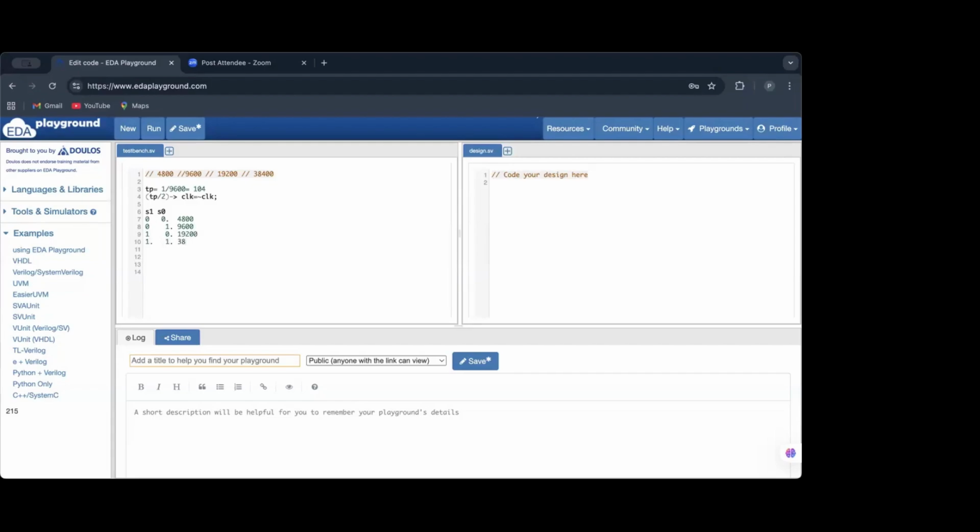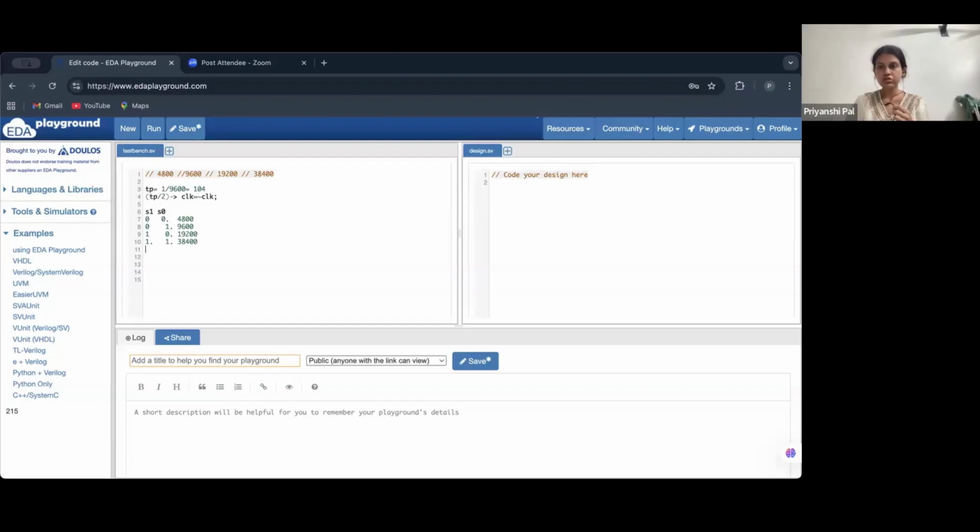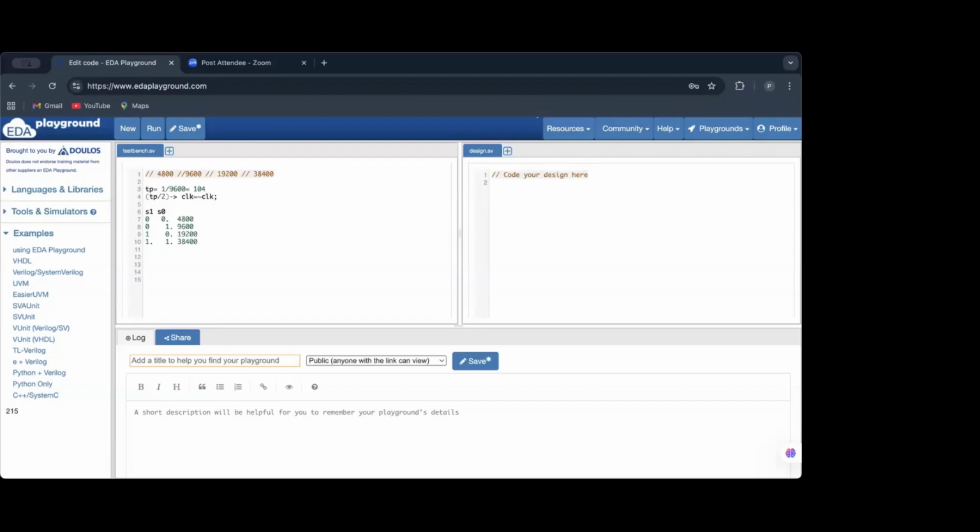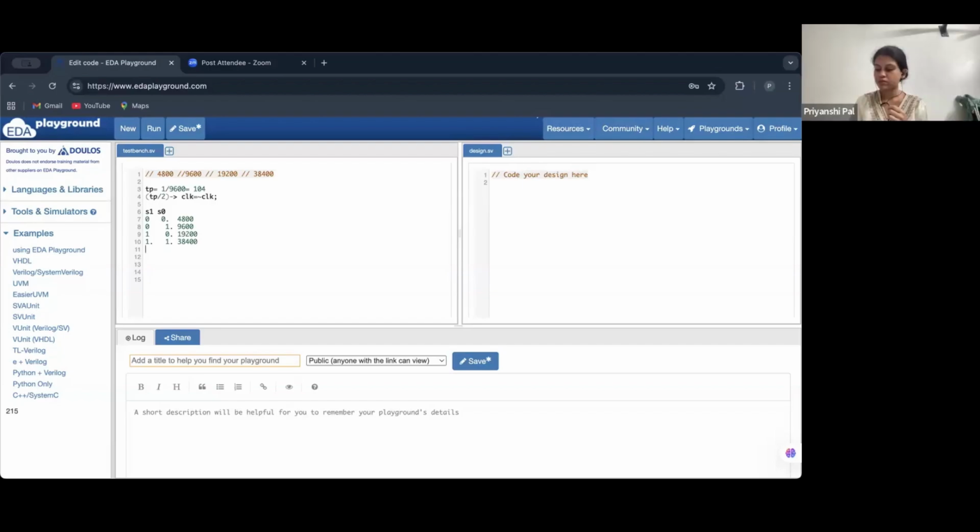So you know about UART and USART? It's for synchronous, but I haven't heard about it. USART. Yes, the normal UART is asynchronous. It means no clock, only TX and RX. But USART can be synchronous or asynchronous, which uses the clock in synchronous mode. So here we don't require a baud rate for synchronization.